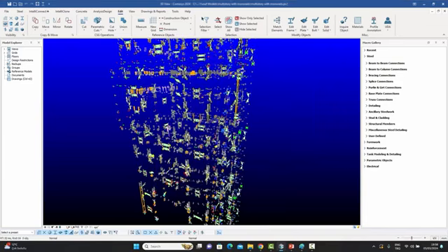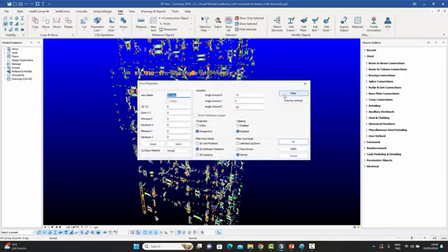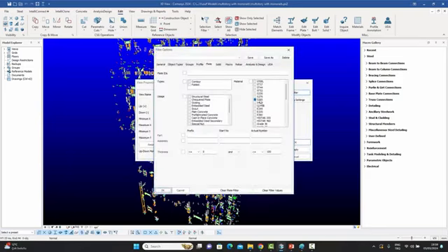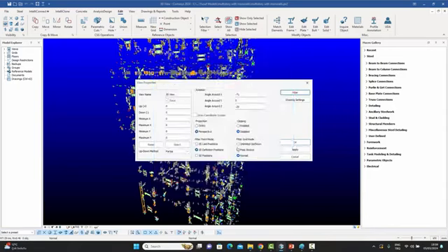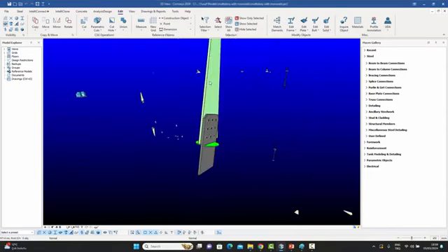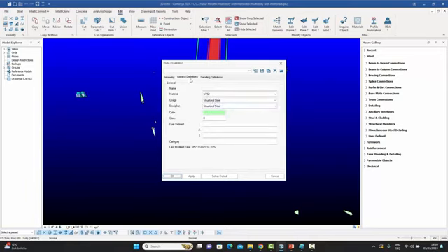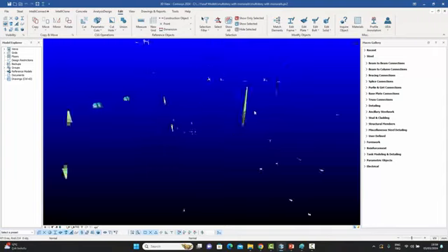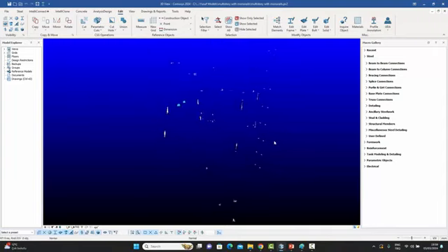Now, like I said, this building mostly uses this one. But if I want to see if I've by mistake left some, I can use this not option, which means show me any plates which are not 355. And if I do that, then certain plates come up, and I can double click on them and see that yes, the material has been forgotten as some other material, and I can either make the necessary changes or leave it at that.